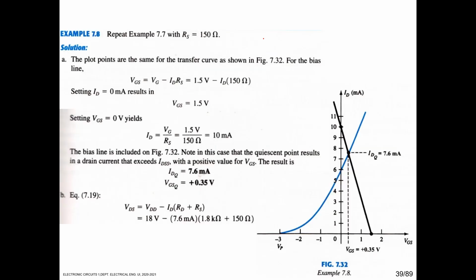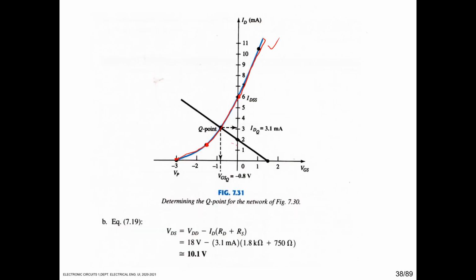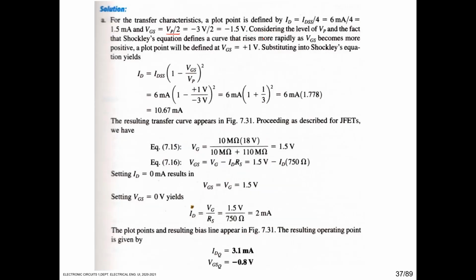And then another is we have to plot the circuit characteristic, the black line. Or here, if you want to put another point in the device characteristic, simply, for simplicity, you can use the Shockley equation.